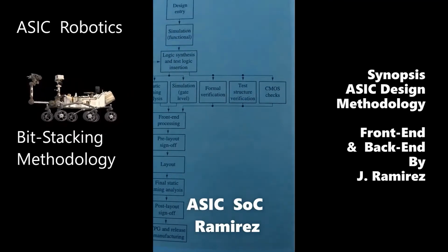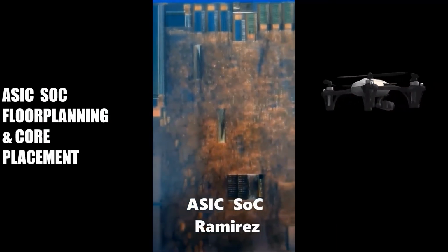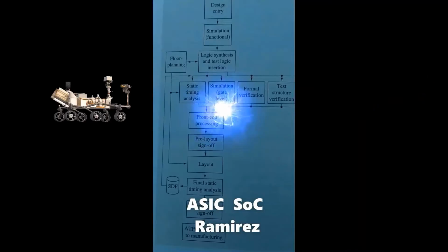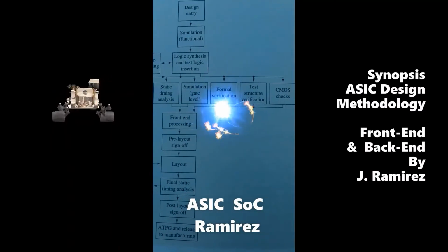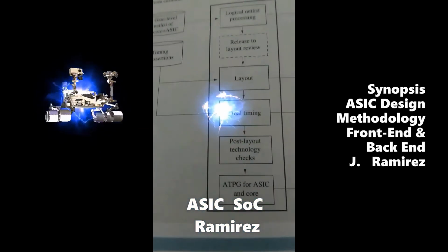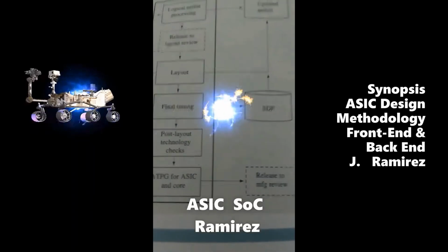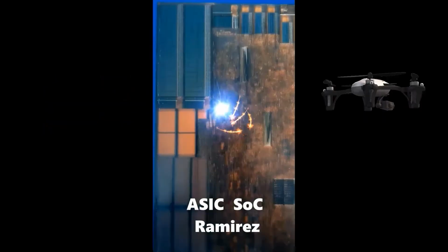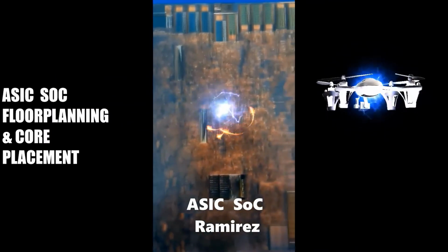Bit stacking methodology addresses the need for greater chip density and performance when bit stacking is applied to designs with a high data flow content, such as processors using large arithmetic logic units, registers, multiplexers, and shifters. The utilization of available gates, or density, is improved.